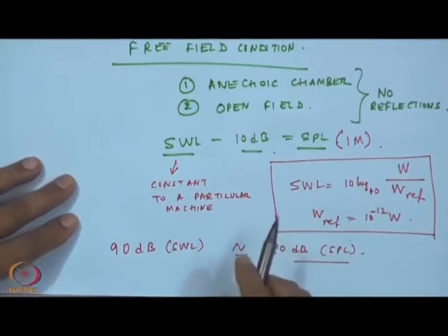So, through this example, I just introduced you to a few concepts of room constants, which is very important in a machinery environment, as we will be called to monitor the noise of machines which have certain defects. So, we have to be careful about the conditions in which we measure the sound pressure level, because if the environment changes, the sound pressure level will obviously change, and like we saw, it depends on the directivity and on the room constant.